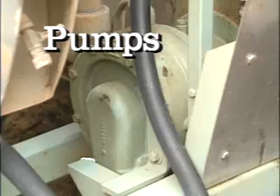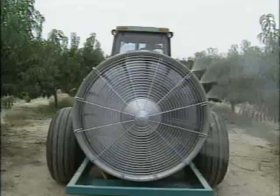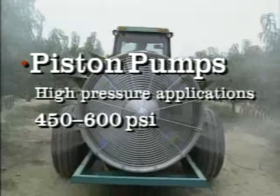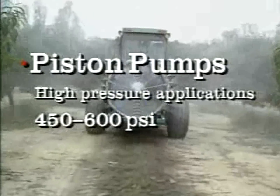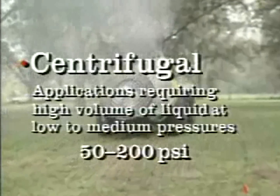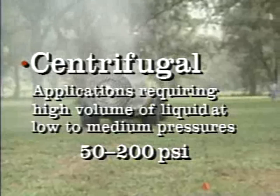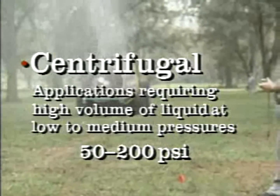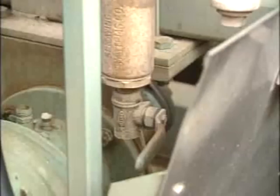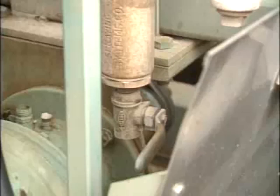Pumps used in air blast sprayers are usually piston or centrifugal pumps. As a general rule, piston pumps are used for high pressure application, up to 600 pounds per square inch. Centrifugal pumps are used for applications requiring a high volume of liquid at low to medium pressures, 50 to 200 pounds per square inch.